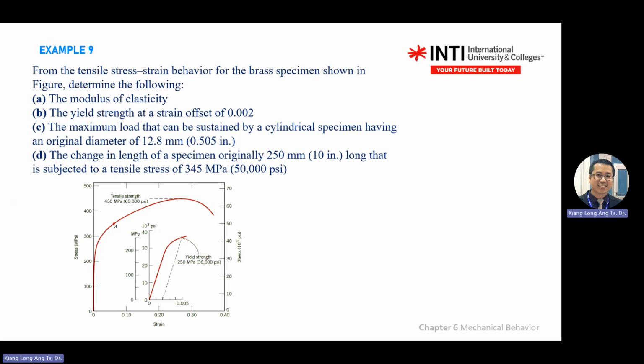Okay, so you have the 0 point here. This is delta x, here is delta y. Substitute the values there: you take 200 megapascal divided by 0.02, and you get your Young's modulus. Put it in gigapascal, normally, for metal. Press your calculator and you get the numbers.